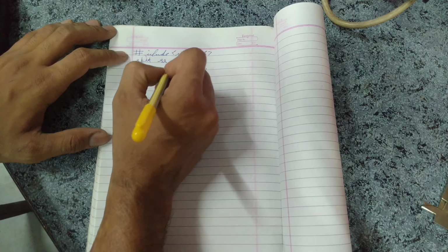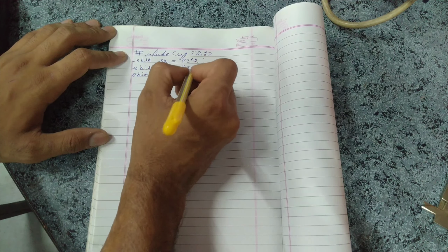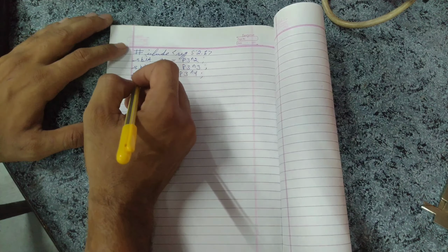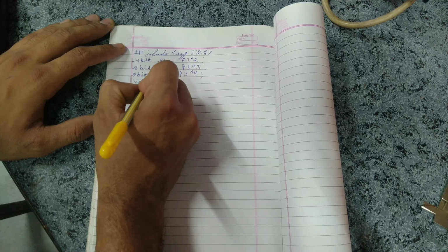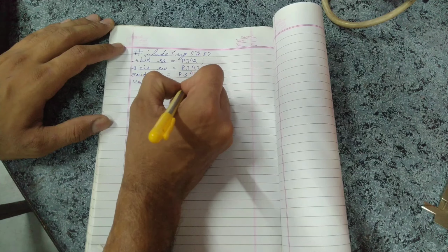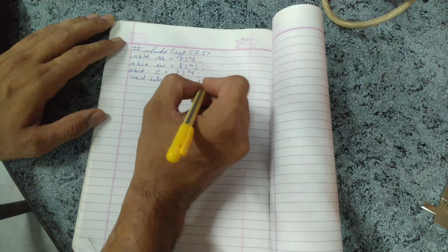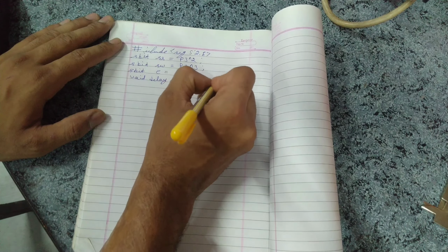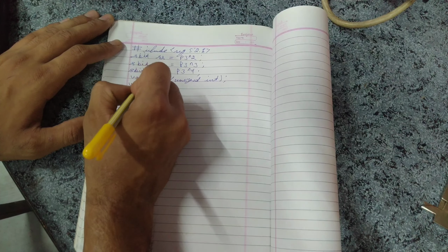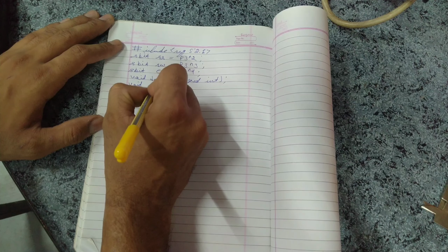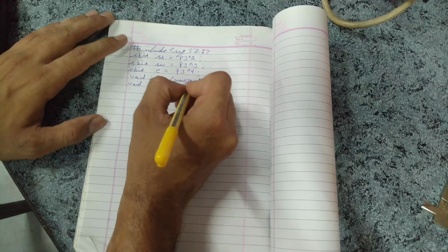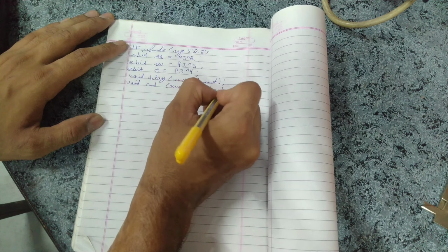We use the enable pin here from port 3 by using bit number 4. Then we present the delay, which is used here, that is unsigned int, which is 16-bit. And we also use the void command, which takes an unsigned char here.